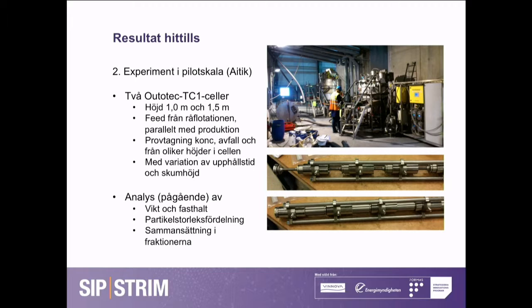Except for that, we did tests on a pilot scale. We used 1 cubic meter cells from Outotec. We changed one of the cells towards a higher height and ran in parallel to the flotation of the concentrator plant.